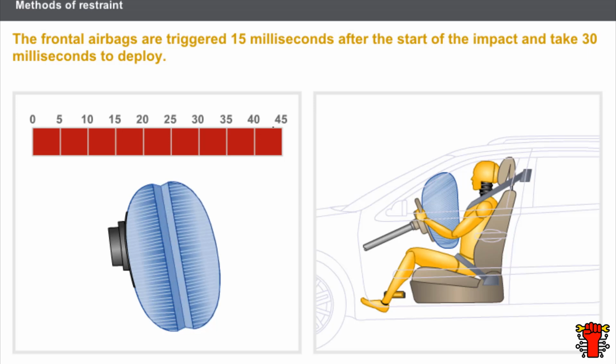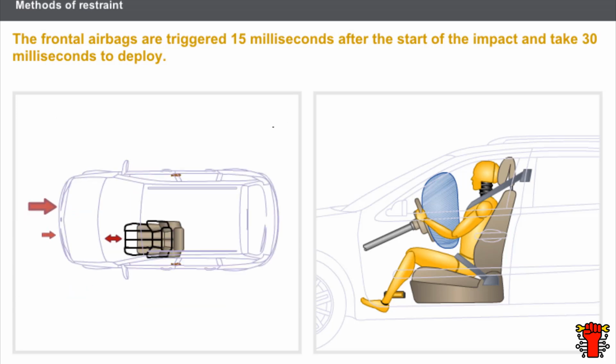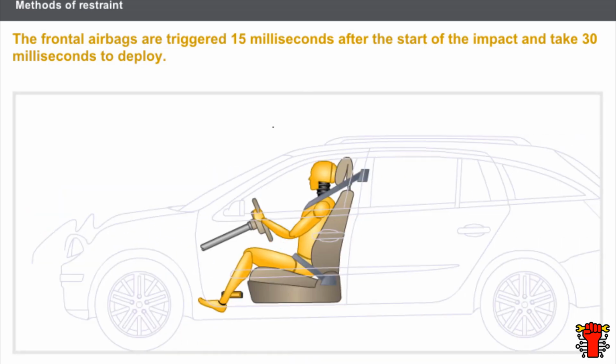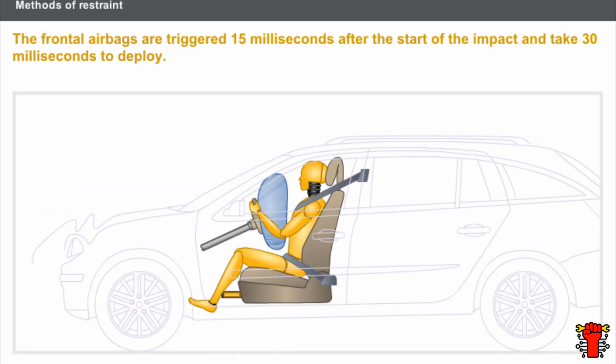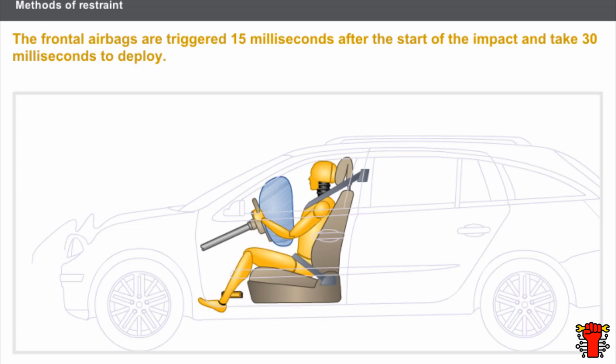Some airbags are double volume airbags and have two independent pyrotechnic ignition modules controlled by two separate trigger lines. Full or partial deployment of the airbag is determined by the severity of the impact and by the position of the seat. If the seat is in the fully forward position, the airbag deploys using an airbag volume just sufficient for the size of the occupant.